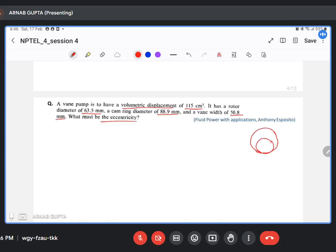So basic construction of a vane pump is like this. So this is the cam-ring, and this is the rotor, and you have some slots that are made around the periphery like this, and the vanes are like this. So this rotor is rotating, and this particular distance between the centers is your eccentricity.